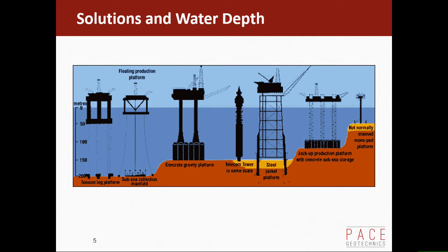A steel jacket is probably the most common sort of structure that you will see on an oil platform. They are landed on basically just the lattices. That section is landed on the seabed, and then it's piled down into the seabed. There are guide tubes to pile it down, and the piles are grouted or swaged into the guides at the completion of driving, and then you put the topsides on.